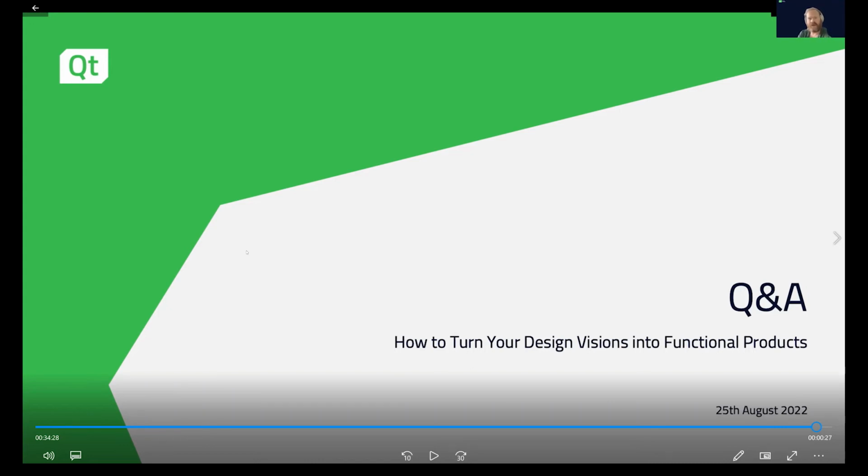The final part of that question: can it be reused in multiple Design Studio projects? That's something where that's still a little bit lacking, let's say, in Design Studio. Design Studio itself does not have these strong collaboration features that Figma does. So of course you can reuse QML components, but there isn't a nice UI provided to do that automatically. If you have those components in a Design Studio project and you want to move them to another Design Studio project, you would have to physically copy them across from one project to another.